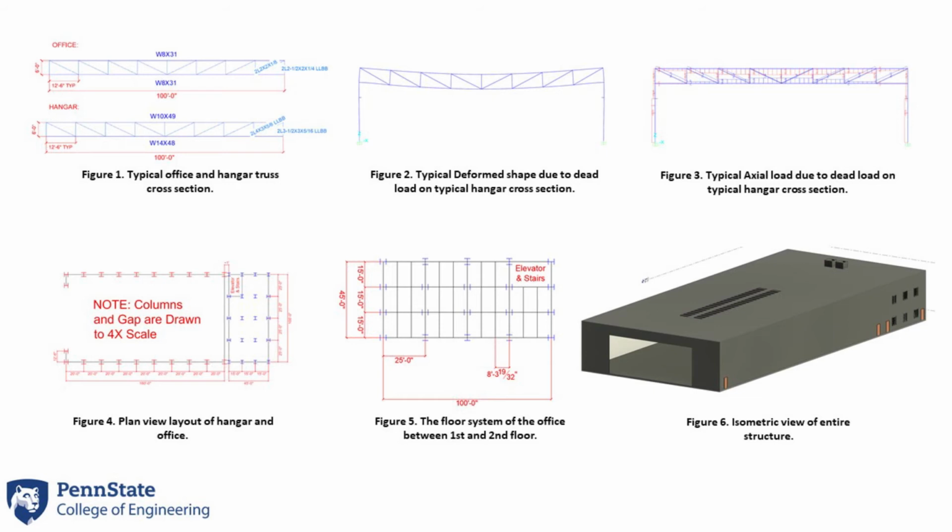Phase 3 of the design process involved taking these force load values to size members for strength. One thing that affected these designs was the type of connection that would be used. The team decided on these connections through both an analysis period and meeting structural stability on the SAP model. It was decided that the top and bottom chord as well as the columns would need to be treated as beam columns as they were required to carry moment, but the interior web members and bracing could be tension or compression members. The team then made design sheets to check limit states and design all members for strength.